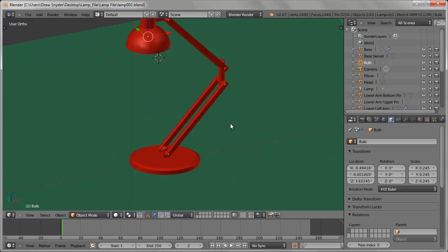The groups in Blender aren't like the groups in other 3D modeling programs, so we're actually going to use empties to create groups. In other 3D programs, the creation of groups basically uses an empty as well, but the entire process is kind of hidden and automated. So the very bottom, the base, we're going to leave that alone. This is going to be the parent, the main part that drives everything else as we work on this rig. And then the swivel, we'll come back and do that in a minute, but let's start with the lower arm.